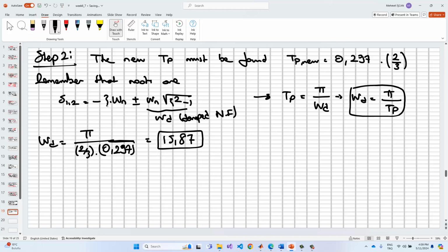First of all, we have the zeta and the omega n values in here, right? And then we can draw the root locus, sigma j omega, right? And so what's our dominant pole in here? The sigma must be equal to 5.145, and so the pole desired is equal to what?